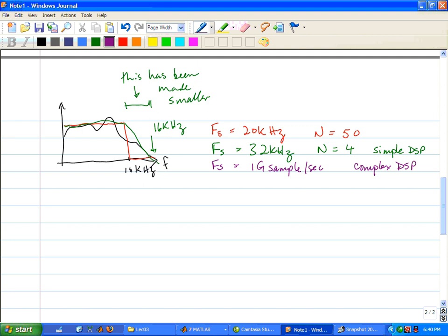And as we said, now you have clocks that you have to deal with. You have to generate a gigahertz clock. You're going to have to manage data on buses moving that fast. You wind up with a much larger and more complicated DSP than you would have had otherwise. So there's such a thing as overkill in this situation.